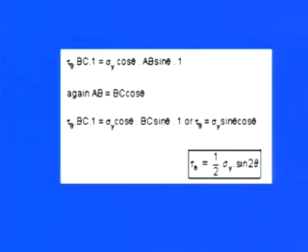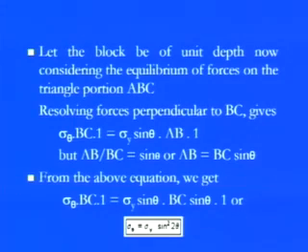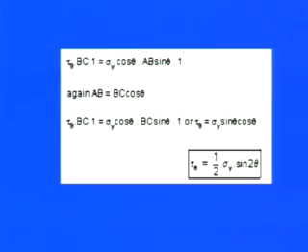Now you see that sigma theta, which is sigma y sine square theta in the previous case, and tau theta, which is half of sigma y sine of 2 theta, come only from the influence of pure normal stress.